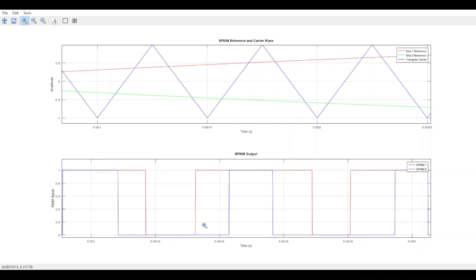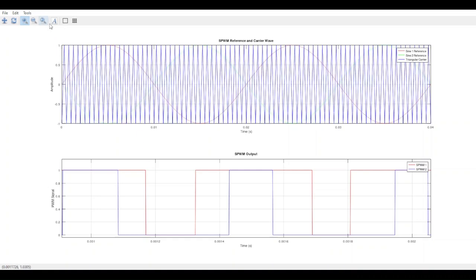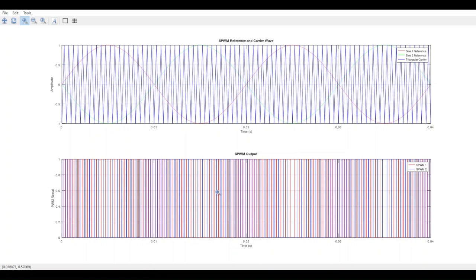And when we're talking about the first half bridge, this is going to directly determine the PWM of the top MOSFET. And the bottom MOSFET is going to be complementary of the top MOSFET. The same goes for the second half bridge, where this determines the duty cycle for the top MOSFET, and the bottom MOSFET is going to be complementary of the top MOSFET. We'll look at that in more detail later on. All right, and that's about it.